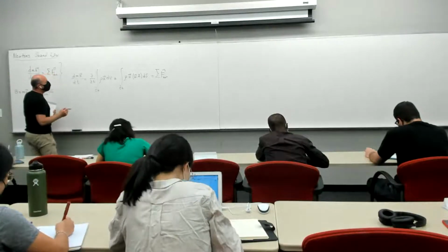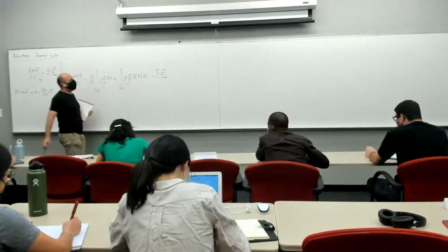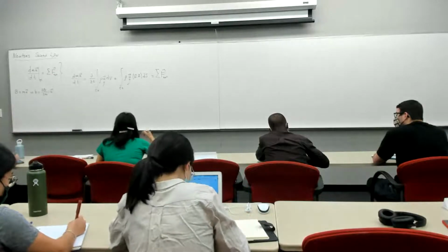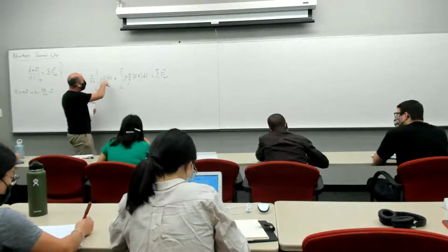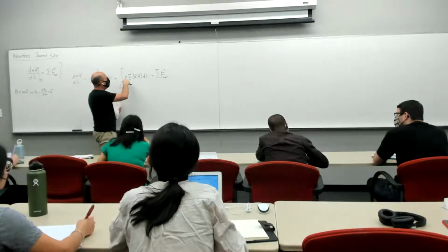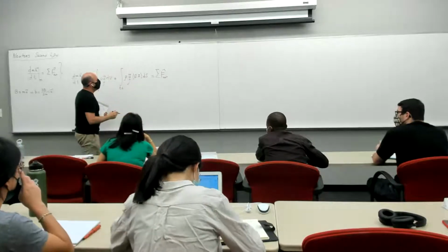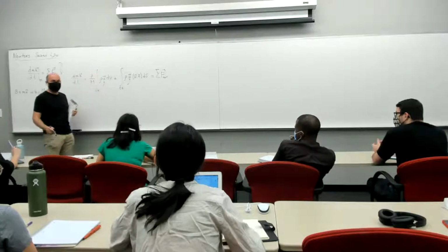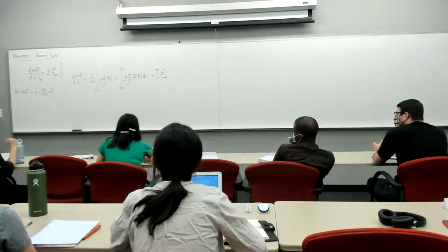So all you had to do is just put in your intensive property over here. Okay. When we had mass, the intensive property was 1. So we had d dt of the integral of rho dV, and over here rho times 1 times u dot n dS. But over here you have something interesting, rho u u dot n dS. Okay. So we'll talk about how we evaluate that.